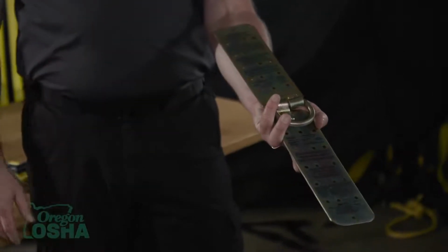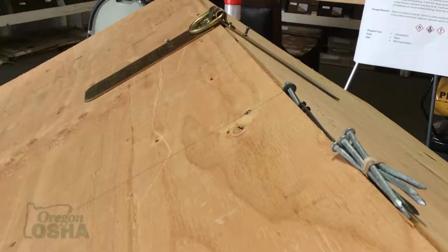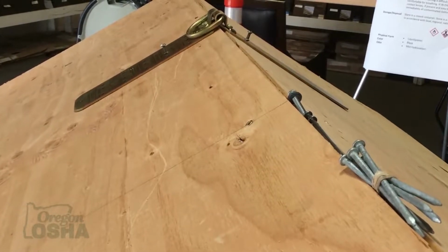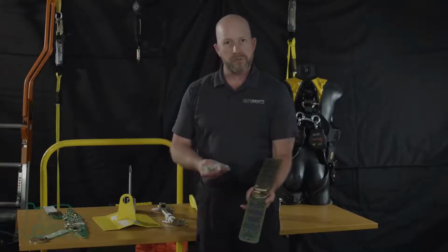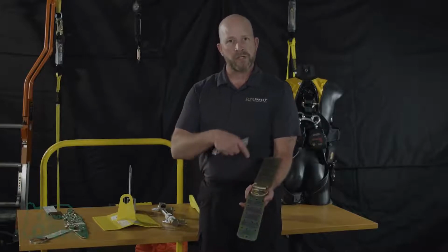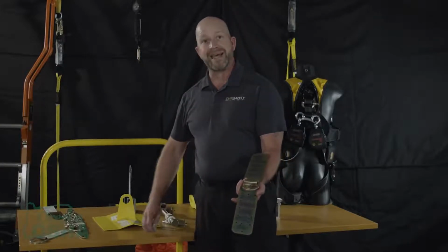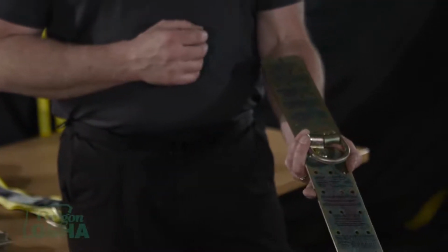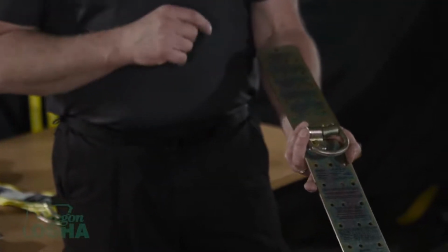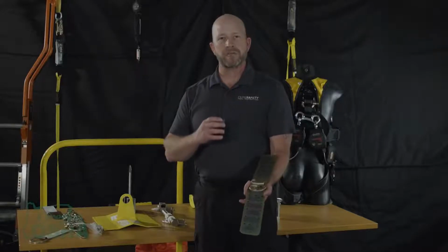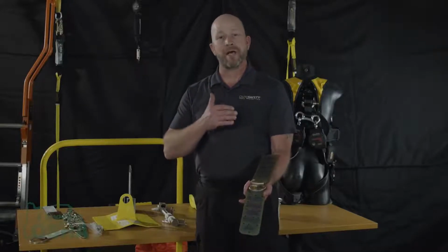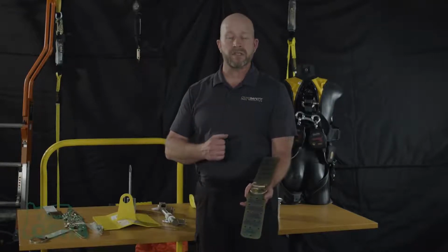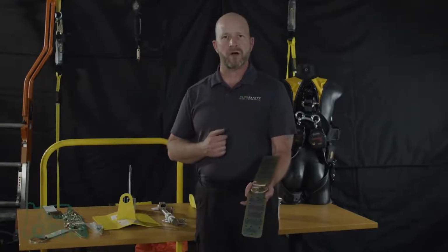Most of the time, the anchors will also come with, especially on the residential side, the first set of fasteners, the starter set. It will come with the screws or nails appropriate to install this in the substrate that it is designed for. Again, always consult the manufacturer's instructions on the minimum size and strength of the substrate, and either have it evaluated by a competent person, or